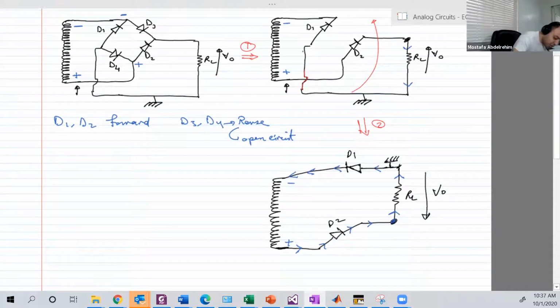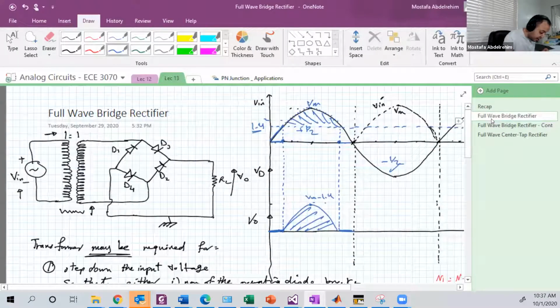We can do the same here also. So we start from the positive terminal, valid because from P to N, then from up to down, continue, cross the bridge, D1 from P to N, valid until you reach the negative. We are saying that this should be a full wave rectifier. And yes, it's a full wave rectifier now, because in the negative half cycle, there is a current flowing in the resistor. But is it the same direction as the current that was flowing in the resistance in the positive half cycle? Let's check. Let's go back to the positive half cycle and see.